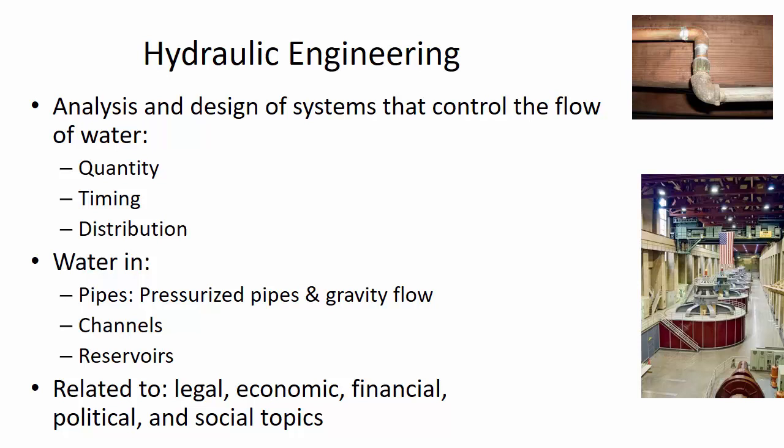If you're sending water from here to there, if you have a really small pipe, the water won't have as much pressure when it gets to there. So you have to figure out what are the requirements at the point of delivery. You know, where you're going to be withdrawing the water, do you need the pressure to be 250 kilopascals? Does it need to be 500? And how much water are they going to be using there? And so there's economic consequences having to do with optimization.